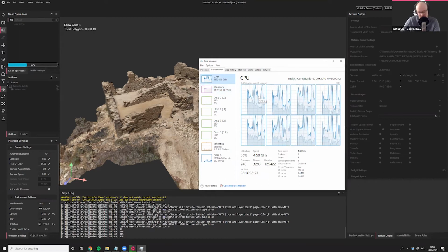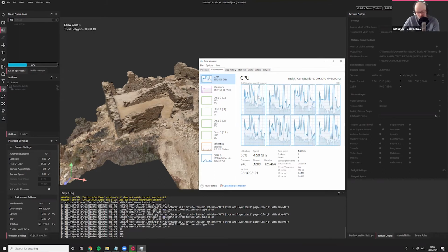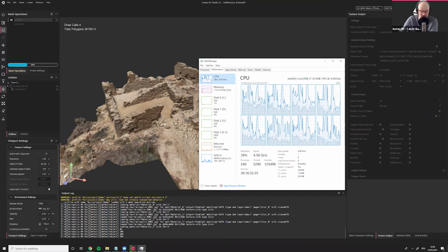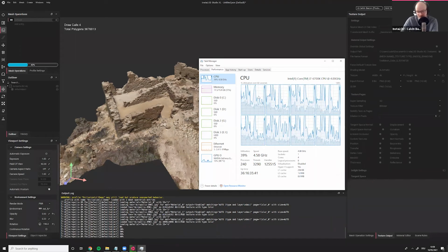Now again, the remesher is doing a full reconstruction, right? As if an artist were to do the manual retopology. And I'm sure you guys know how much work that is. Again, on top of that reconstruction, InstaLOD is doing a new UV unwrap for that new mesh, the reconstructed mesh. And it's also baking the textures down into a single 4K map.